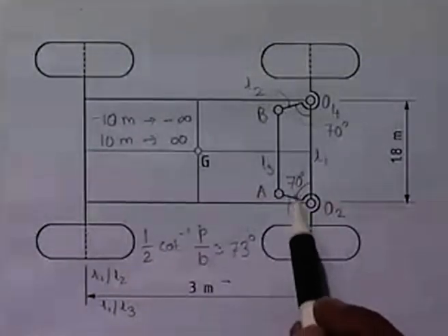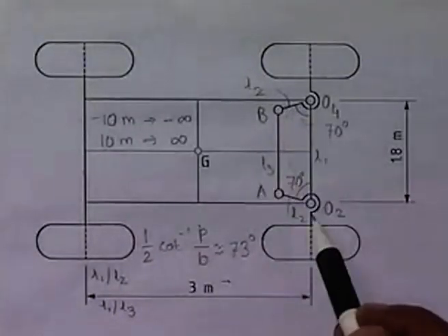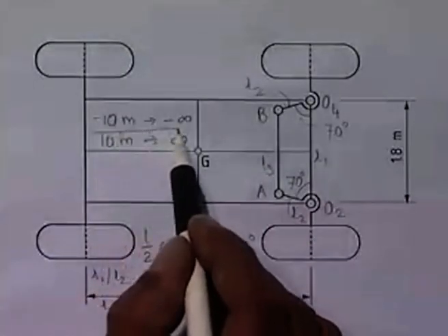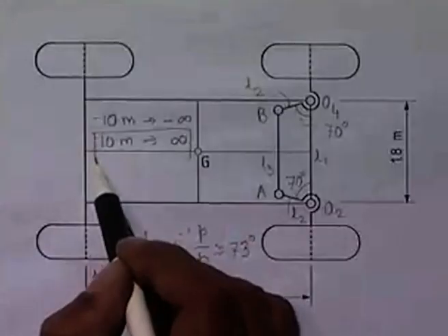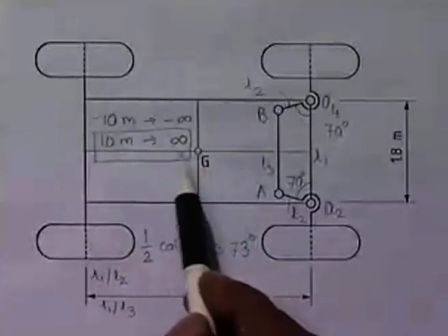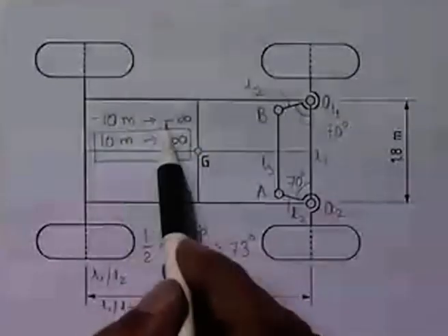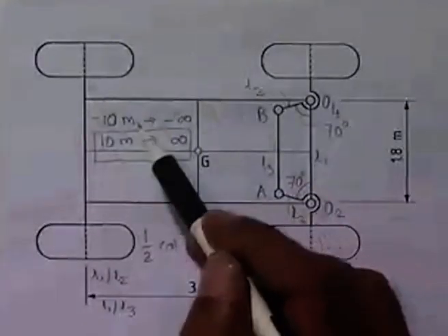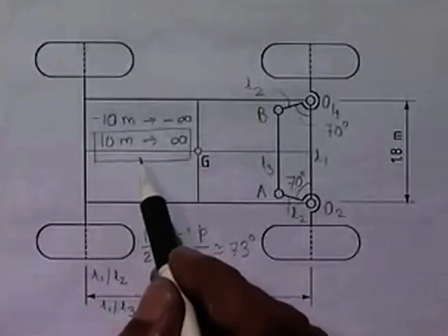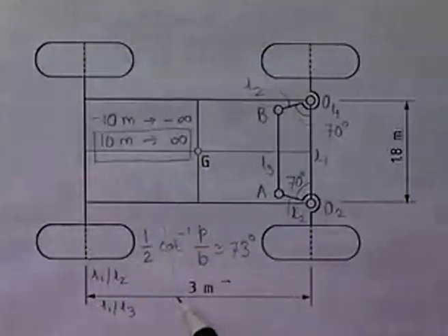Of course, the symmetry of the linkage ensures that I need to consider only one kind of turn, say from 10 meter to the straight path. Minimum 10 meter radius for G and straight path for G, because the negative part, that is the other direction of the turn, will be automatically satisfied. Now the question is, which radius I should try to satisfy the steering requirement. For that, we go back to our Chebyshev accuracy point.